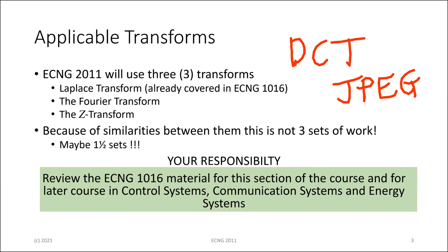So it gets the raw information, all of the spots, the pixels of the camera, and it does this special transform called a discrete cosine transform and converts it into, after a little bit of manipulation, a JPEG. If that wasn't possible, you would need too much storage for every picture that you take on the phone. The JPEG is substantially smaller in terms of file size than the original picture that came off of the camera once it gathered the information.